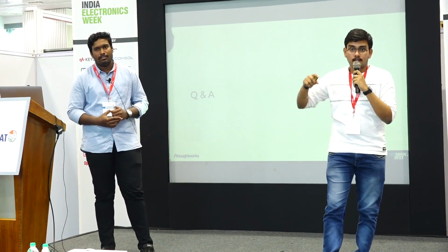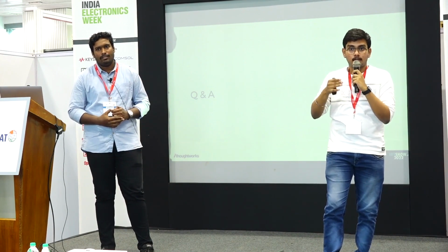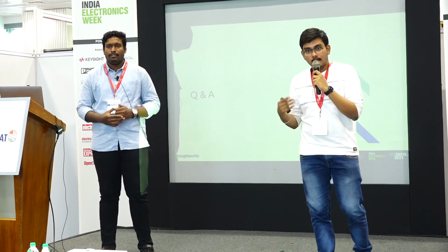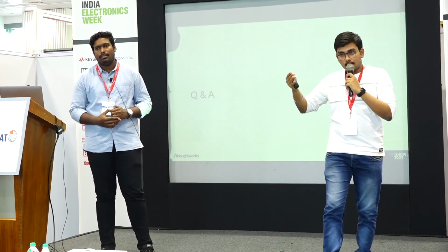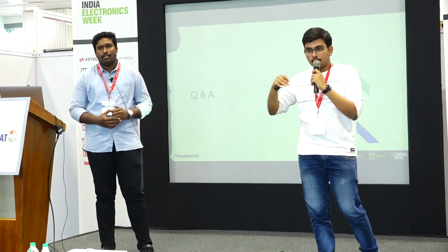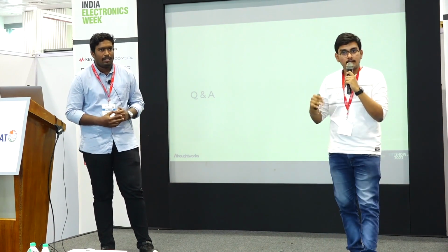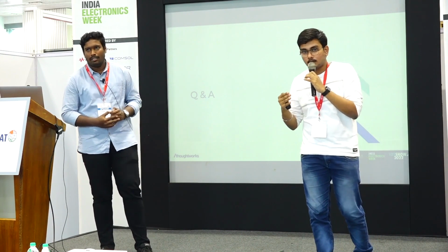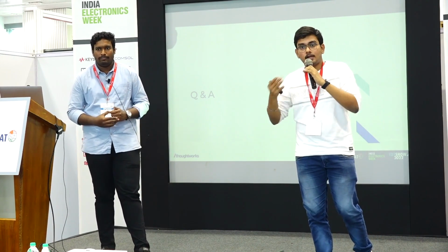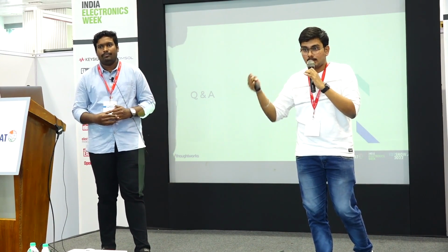For example, as Praveen was telling, the ODOM data tends to deviate from the original as time passes. Cumulative errors will be there. While running it for a longer time, that's why we are aiding it with multiple sensors, to make the localization more precise. Otherwise, it will work, but it might fail at times. It might fail immediately when it goes inside some kind of obstacle. It will fail to localize, and that's why we are aiding with multiple sensors.